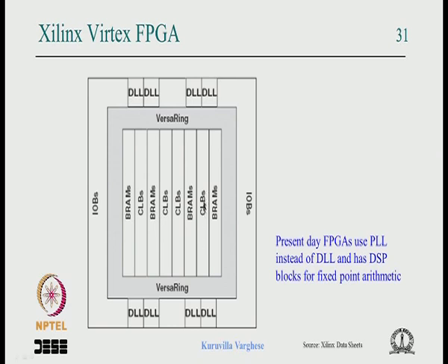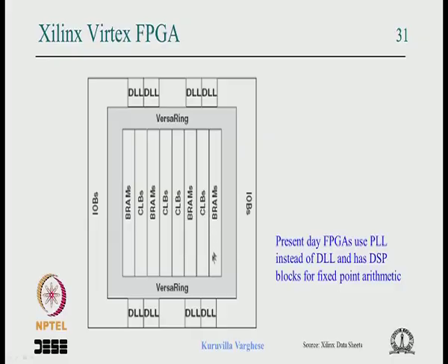We will look at this in a little more detail, because there you can do a lot of optimization, you can understand, you can debug, you can find why certain things are happening, or why it occupies so much more area or so much less area and so on. When you have done a design and look at the resource utilization, you may wonder why it has taken so many lookup tables. We will be able to figure it out by the end of the lecture. So we will look deeply into this CLB and touch upon the other standard basics.